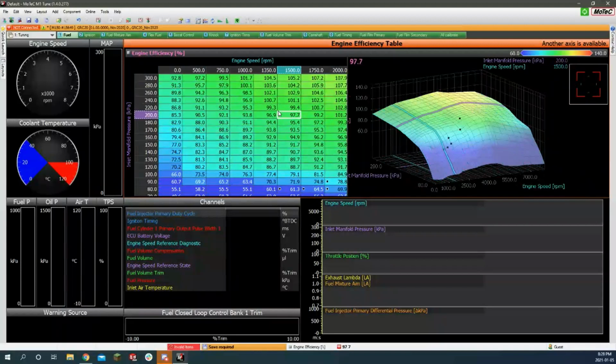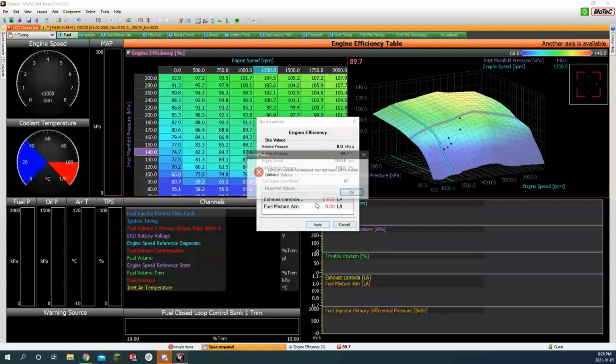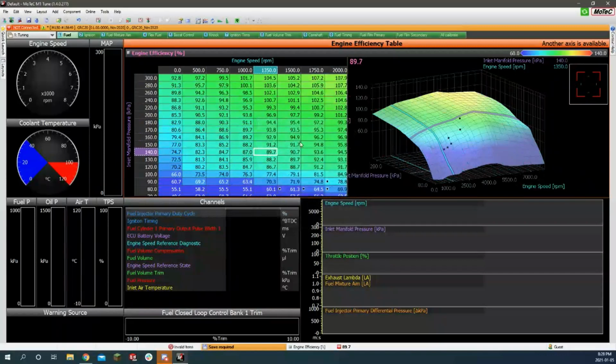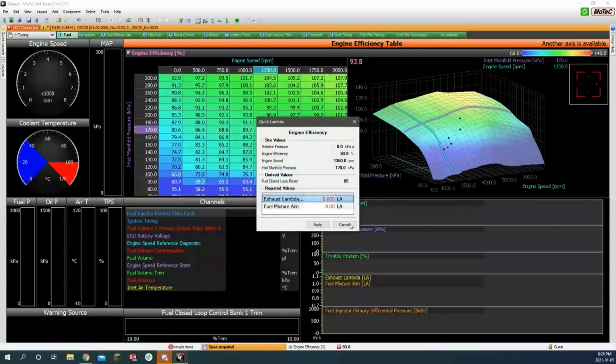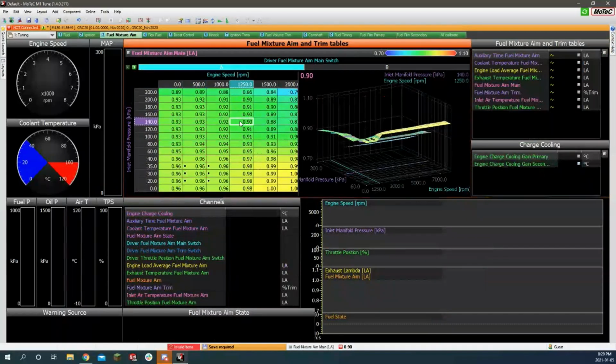The Q function works here too. This is where it's super useful. Like you can press... it doesn't work. Yeah, I get it. Oh, it's because the engine's not running. Lambda's not going. But basically, you go through these cells. If you get your engine centered on this cell and you really tune in, like exactly what your oxygen sensor is getting, a nice consistent reading, you press Q, and it does the math and sets this value to what it needs to be in order to get your air fuel ratio right on your target, which is this table.